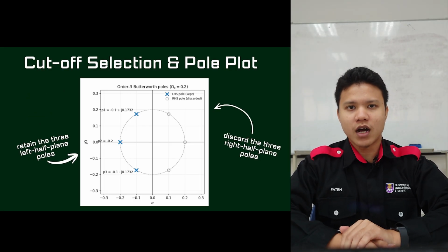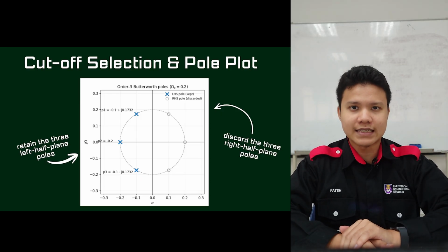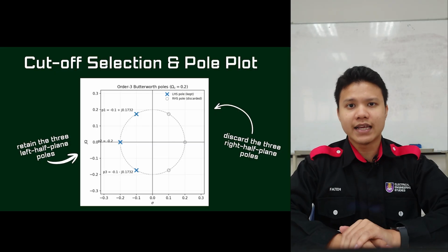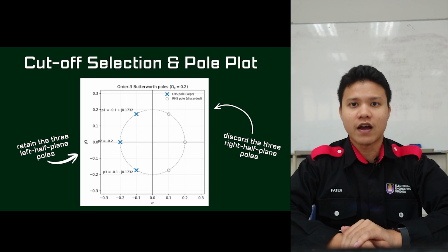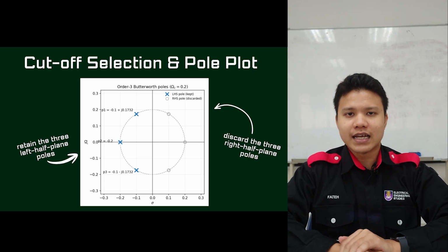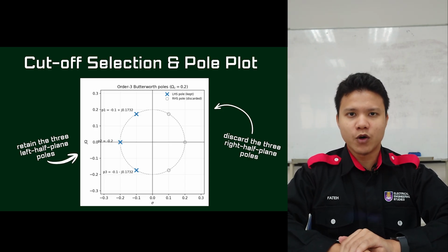Rounding our order up from 2.22 to 3 means our design constraints no longer cross at a single point. Instead, they give us a flexible operating range for our 3 decibel cutoff frequency between 0.1808 and 0.2154. We select a clean, convenient value of omega c equals 0.2.